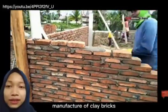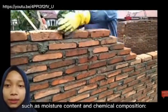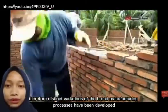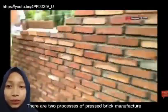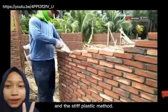Manufacture of clay bricks. Different clay has different characteristics, such as moisture content and chemical composition. Therefore, distinct variations of the broad manufacturing process have been developed, and these are easily recognized by the finished product. Pressed bricks. There are two processes of pressed brick manufacture, the semi-dry method and the stiff plastic method.